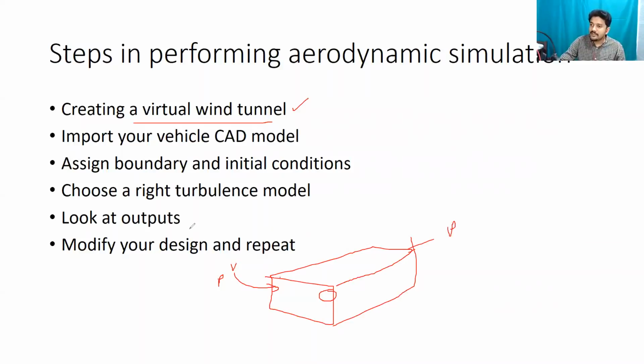And then what the CFD solver is going to do is solve the CFD equations. When you solve computational fluid dynamic equations, you can get the velocity, pressure, and temperature at each and every point that you specify in your computational domain. The points that you specify, that is what you call your computational mesh. This is something that you would create before you run the CFD simulation using a meshing software. So wherever the mesh exists, that is where you calculate the pressure, temperature, and velocity.